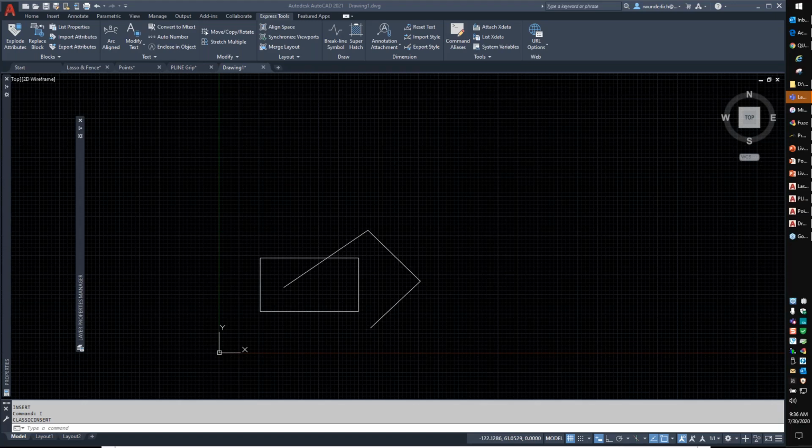Some of the things you need to be very concerned about is that if you're copying and pasting or dragging and dropping data from other drawings that you don't know where they're from, or other drawings that have had issues, you may be bringing those issues into your own drawings. I am a big stickler for, if you need something, create a block out of it. Make sure you take everything out of it. Basically purge, clean, do everything you can to make that block from one drawing as minimal and as error-free as possible, and then you insert it.